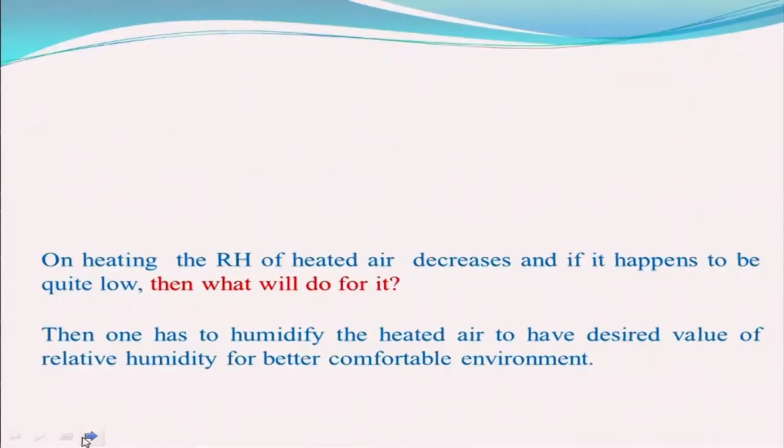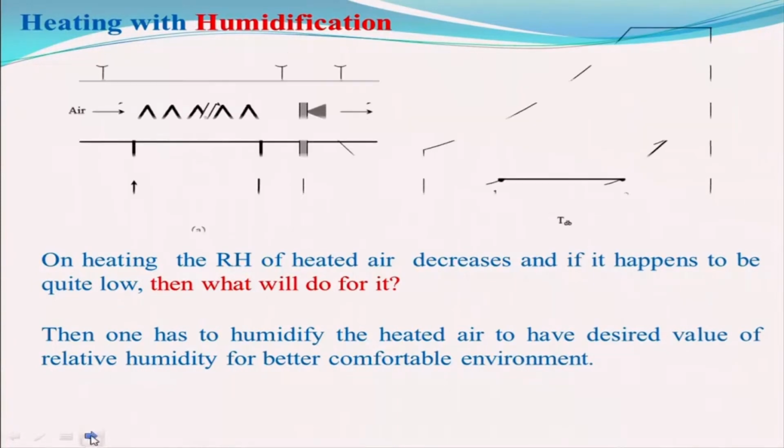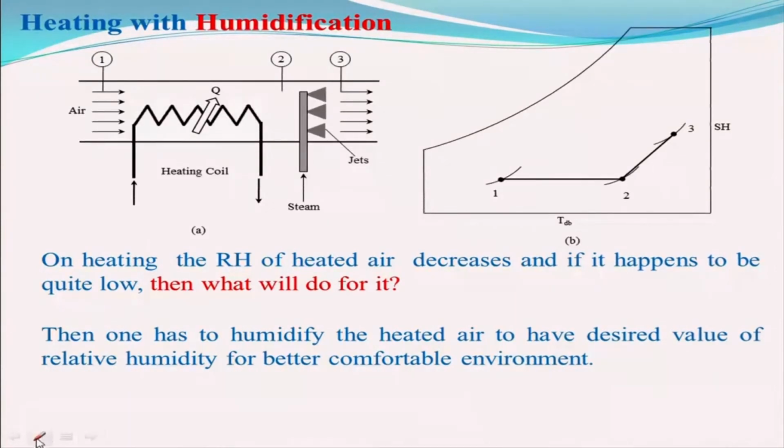So as I told, one has to humidify the heated air to have the desired value of relative humidity for a better, comfortable environment. Let us say heating with humidification, we can do that. You can think of adding, this is the heating coil, and then you can add some steam, and some spray kind of thing you can use, so that it can add moisture.